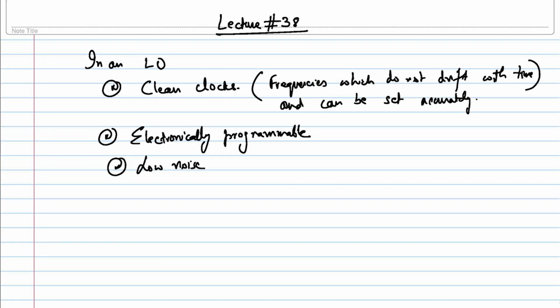When we say that we have to design a clock, what do I essentially mean? Basically, I need to have a framework to generate a sinusoidal signal. Now, what is the easiest thing that you can think of that can generate a sinusoidal output? It's a simple LC oscillator, right? If you have an LC oscillator,